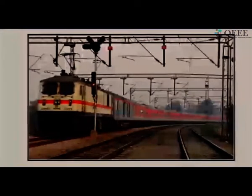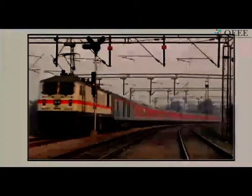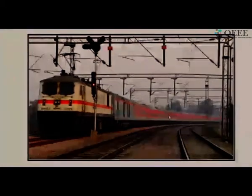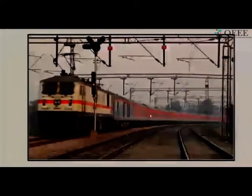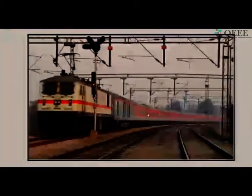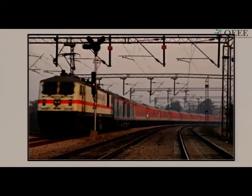One of the items which determines the rate at which heat will go into the coach through the walls and the windows is the outside heat transfer coefficient. So there is energy traveling from the ambient surroundings up to the surface, then conduction through the walls of the coach, and then again from the coach walls it goes into the inside air, which is cooled. So this is the path for heat transfer into the coach. So how do we estimate first the outside heat transfer rate and then also the inside heat transfer rate?